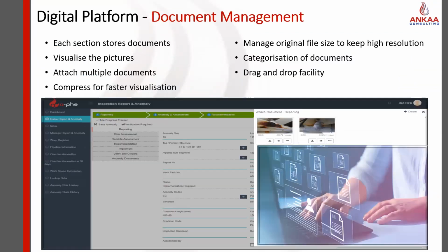You've got the digital platform where you want to maintain all your documentation, integrity documentation. So if you've used documents, P&IDs, your ISOs, any mechanical drawings, you've taken some pictures to show the exact findings, then they need to be at a certain point within the integrity process. And then if the process is improved, you can add on what work has been done and what the latest findings are. And that needs to be kept.